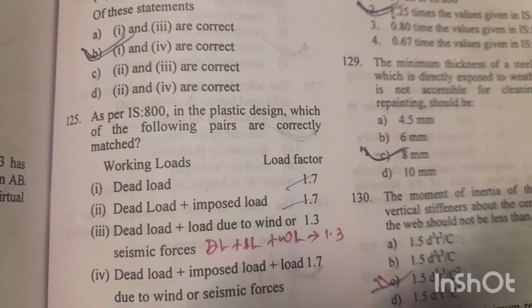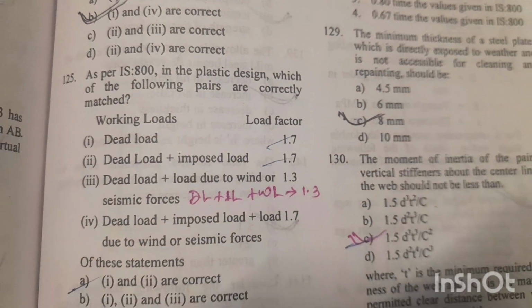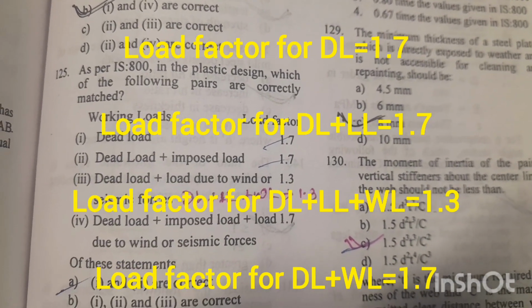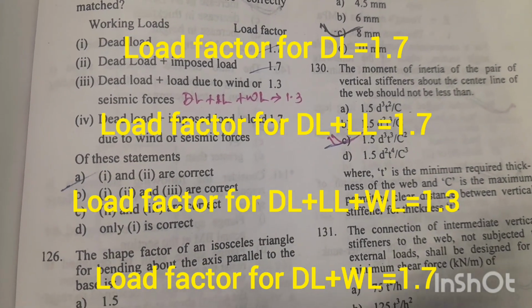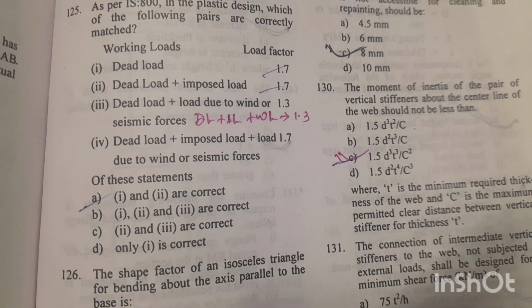Question number 1 to 5. As per IS 800, in the plastic design, which of the following pairs are correctly matched? Working loads and load factor. For dead load, load factor 1.7; dead load plus imposed load, the load factor will be 1.7; and dead load plus imposed load plus load due to wind or seismic force, the load factor will be 1.3, but here it is not given, so only statements 1 and 2 are correct. Option A is the right answer.